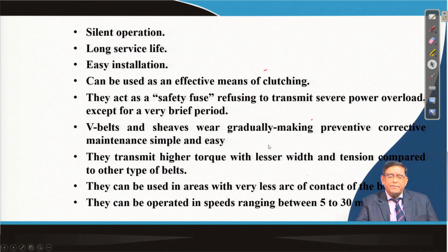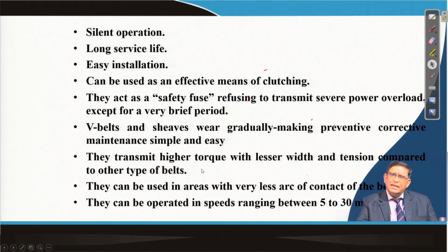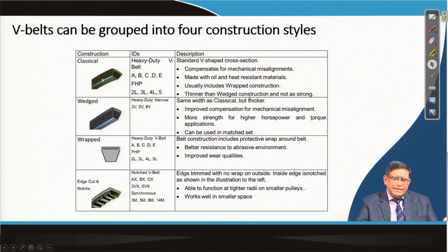So, there are a number of advantages of V belt. You can get high efficiency, smooth starting and running, and it permits a wide range of driven speeds. It is also very clean; you need not give lubricating oil and all that, as in a gear, so it has less maintenance. It is very silent, unlike gears, because metallic parts are not moving against each other. So, you may find a lot of advantages, and these are the different commercially available V belts.